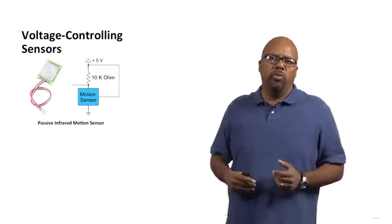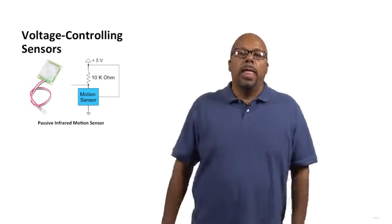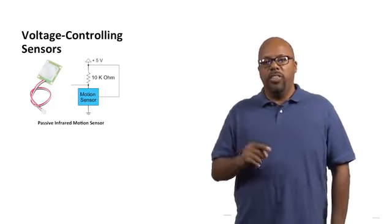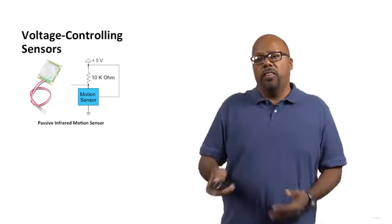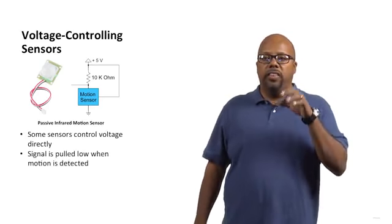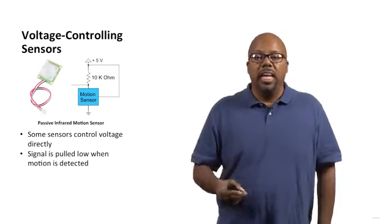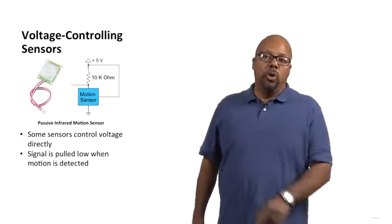Some analog input of the Arduino. So the pin on the top is the one of interest, the signal of interest, right? And that pin is going to have a voltage assigned by the motion sensor. The way this particular motion sensor works is it pulls the signal low when motion is detected. So when it senses motion, it sets that voltage on top to 0 volts. Okay? So that's what's going to happen.